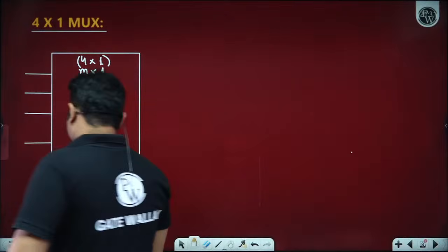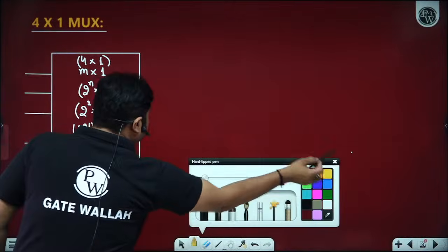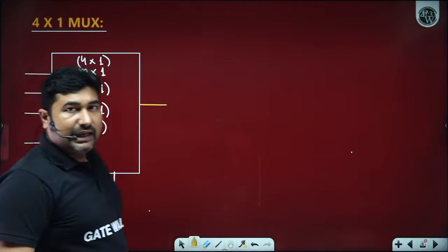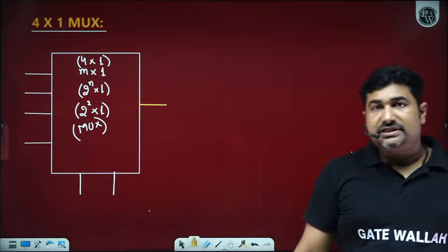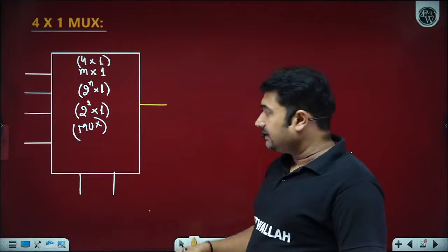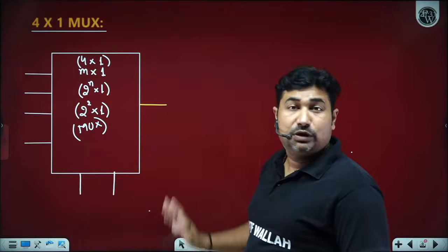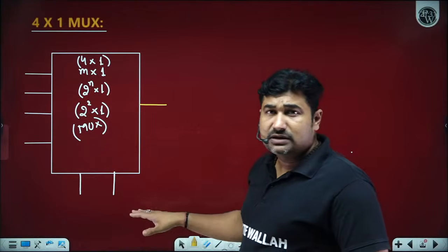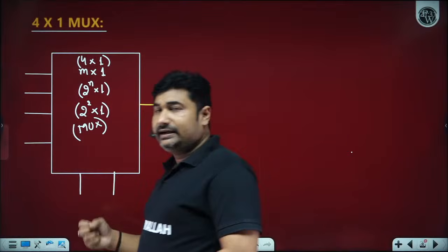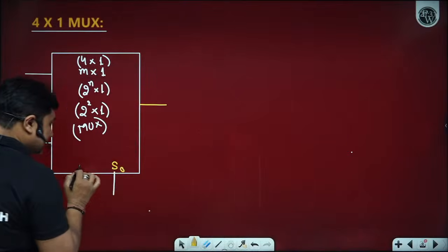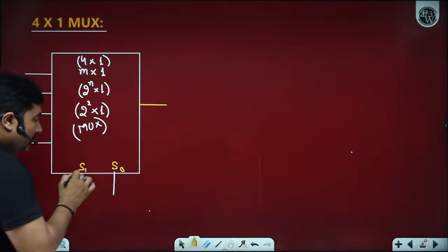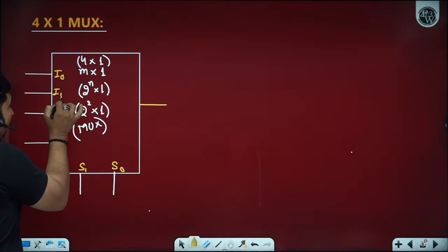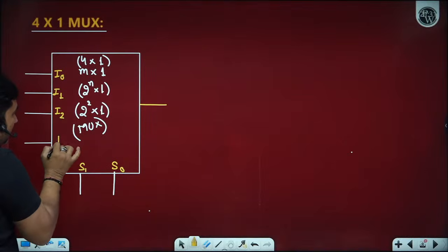Great, sir. Now please observe, in a multiplexer we have multiple inputs, m number of inputs, m is equal to 2 to the power n, where n is the number of select lines, and only one output line. A multiplexer is also called a data selector because depending upon the select line condition, one of the inputs is transferred to the output.